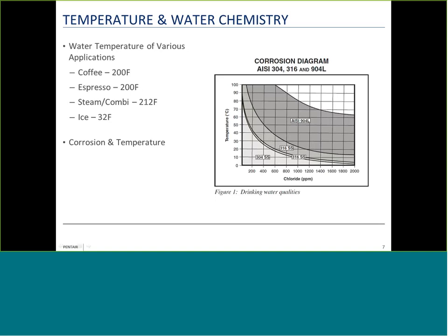And when that number is negative, and the more negative it is, the more aggressively the water will dissolve calcium carbonate off plumbing or inside of components. But as that number increases and becomes more positive over 0, that's showing us that this water will cause scale at that temperature.